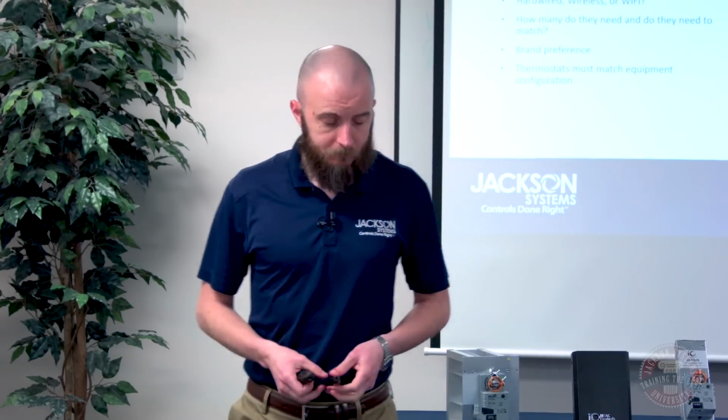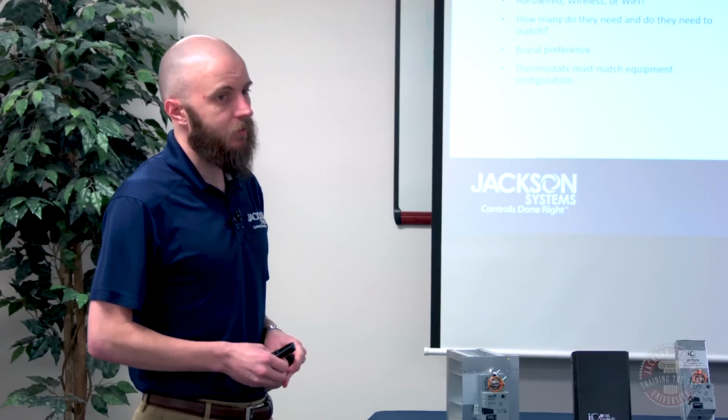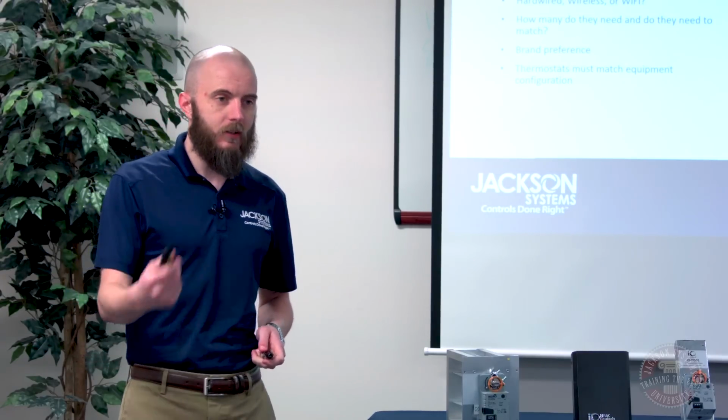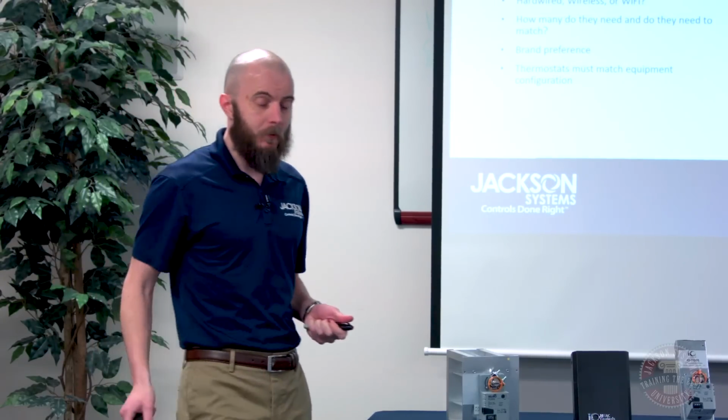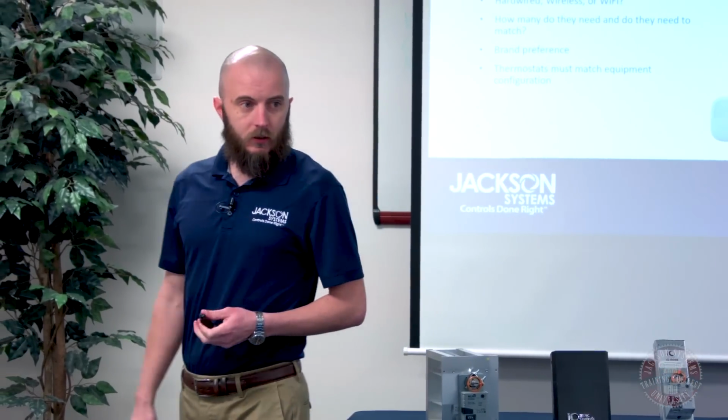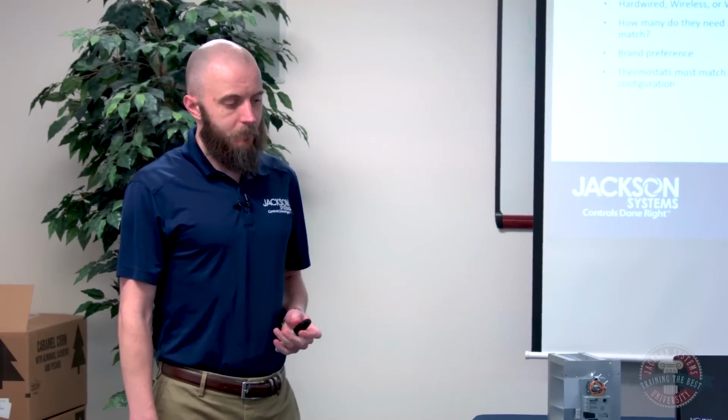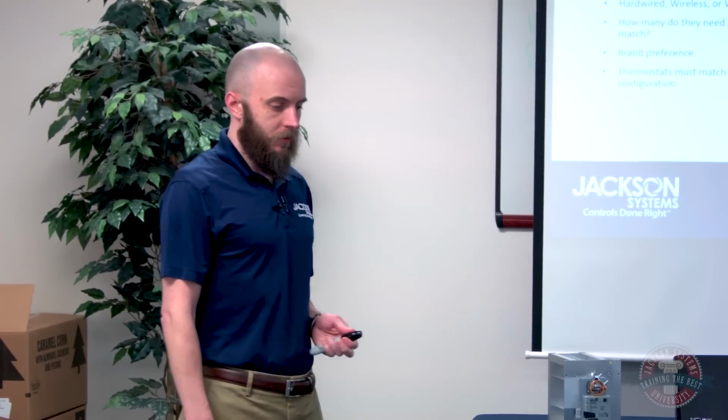Of course, brand preference is a factor. And again, thermostats must match equipment configuration. In most cases, both the thermostat and the zone panel have to match the equipment you're controlling. So if you have heat pump equipment, you're going to need heat pump thermostats and a heat pump zone panel. But any of the thermostats you see there on the screen will work for you, and many, many others.